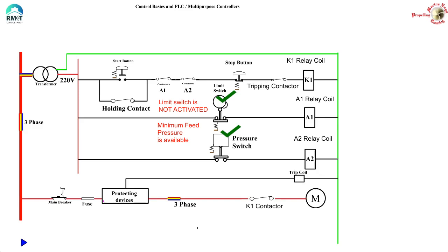But these logics at the moment are based on relays. You can see that the number of conditions and interlocks required for control of a motor are quite limited. The type of inputs are restricted to binary inputs. So a relay based control is quite easy and simple to implement. Now suppose we want to start and control a motor which requires much more complicated logic. Executing the same with the help of relays will become quite a challenge. So we need to move on to the multi-purpose cards.